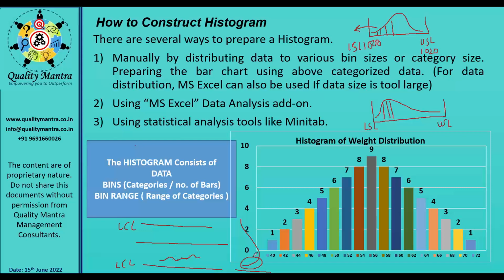Okay. Now if you run your vehicle nearer to the lower limit, because your lower specification limit will be after this, and the control limit has to be within the specification limits. Always remember, control limit हमेशा आपके specification limits के अंदर होना चाहिए, नहीं तो आपके product out of spec बनेंगे. Now the chances of product getting out of spec is more if you run like this. If you run like this here only, the chances of product going outside is lesser. That will define your sigma capability. Okay, that will define your sigma capability.